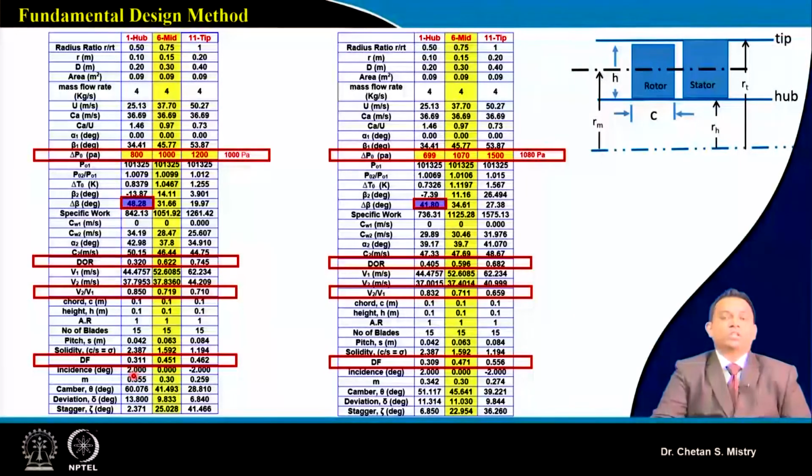Now, as we have discussed, for all designs for axial flow compressor, let it be a low speed compressor or a high speed compressor, we will be using our fundamental approach using the axial sheet design. Here we have all the flexibility to do modification, and we immediately get a cross check or see the variation in numbers visually.